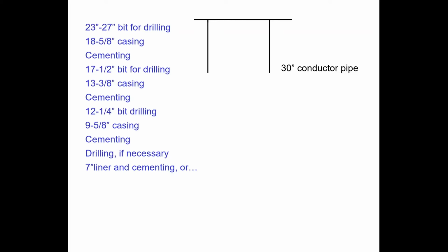Because of the water that we are using for drilling, it makes a big cavity here, and then the rig will collapse. So that conductor pipe protects the shallow sediment.